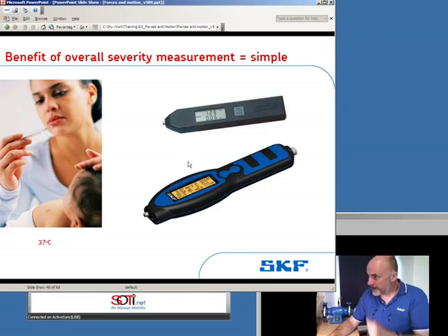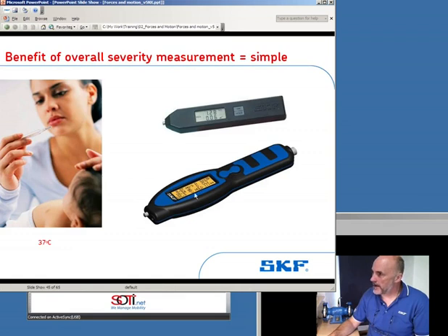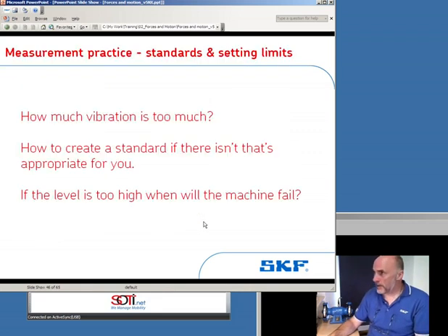We're going to do a session on bearing measurement under the title of acceleration enveloping. So these things are wonderful. The vibration pens, they take a reading for you, the same as we've got here. They take a reading, compare that with the ISO standard, ISO 10816 Part 3, tell you the grade, tell you the levels coming off the bearing, and tell you the temperature.